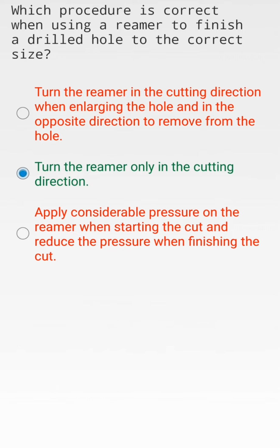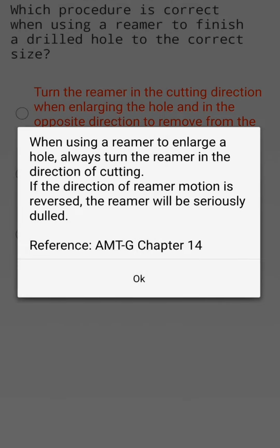Turn the reamer only in the cutting direction. When using a reamer to enlarge a hole, always turn the reamer in the direction of cutting. If the direction of reamer motion is reversed, the reamer will be seriously dulled.